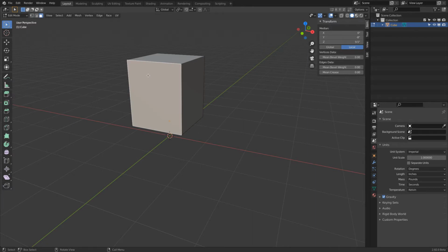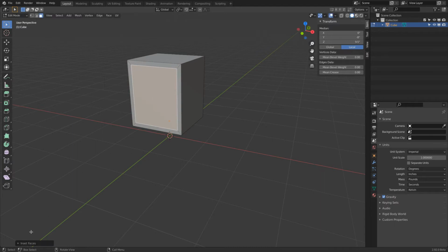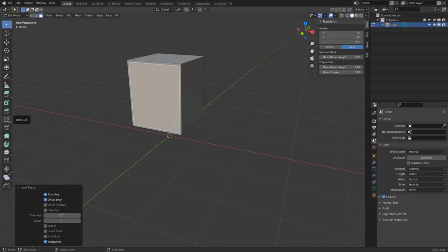Okay. So let's go to edit mode, and here on this face now, there we need to create these two openings. The easiest way to start in doing this is by going to face inset. Let's do an inset, and then we clean this up by entering the thickness to 5 inches. I now need to have a loop cut that goes around. So we have also here the loop cut and the knife. There are some more tools also below.